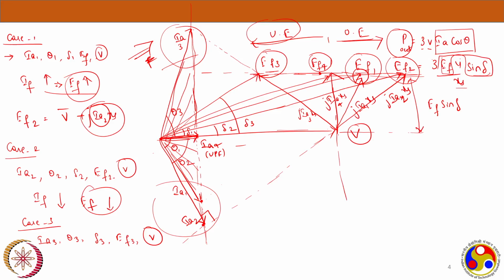They might look complex, but I hope you have got a clear picture of how easy they are. By looking at the phasor diagram, we can see how by variation in the excitation, we can get the different operating power factors of the machine, how unity power factor can be got, how leading and lagging, and how under excitation and over excitation will change the power factors of the synchronous generator.